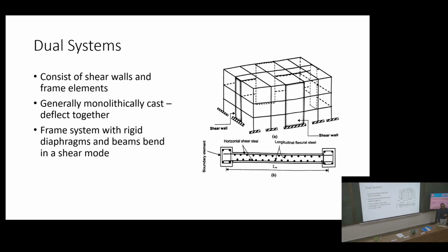So a lot of newer, taller structures with performance-based design are taking this out and putting it right next to the building and not within the frame of the building. That way, you have a very rigid spine. It could be a pivoting spine, it could have some other kind of motions that it's interacting with the frame, but that's what's taking all the lateral forces in the system. So just to give you a glimpse of the future, we are not going to design that, but that's what's really being pushed in different universities. University of California, Berkeley is doing a lot of research, Stanford is doing a lot of research on that.